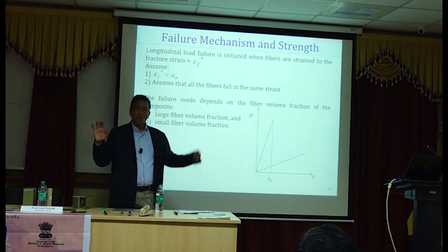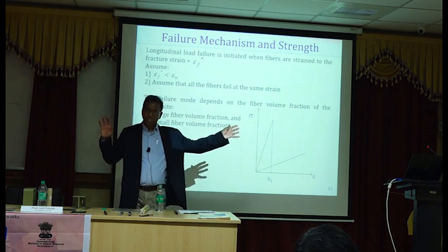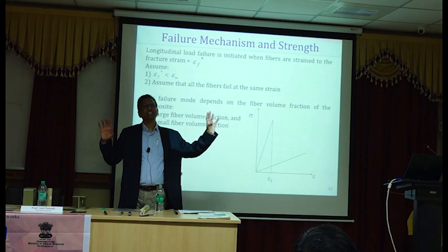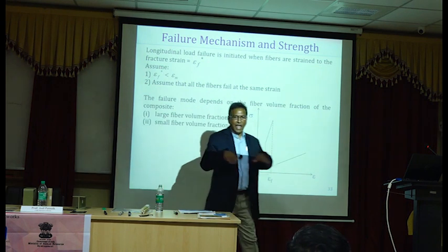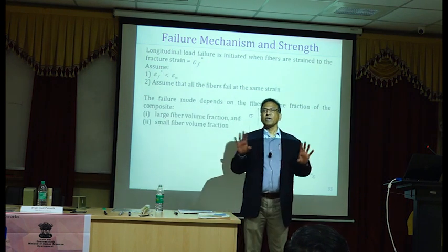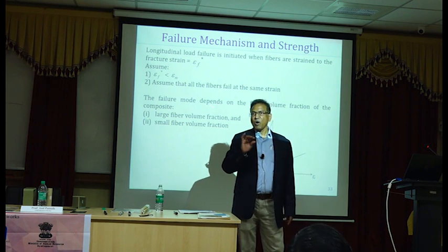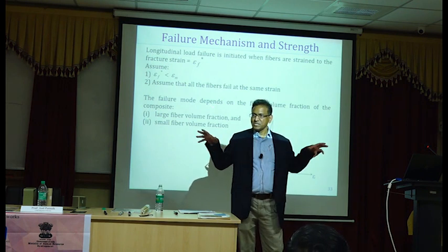Does it make sense? One is an uncracked section. That's where you use flexural tensile strength, which is also known as modulus of rupture, right? So if you don't provide any steel reinforcement, you apply a load, it will crack. It will act like an uncracked section all the way to failure, and it will become two pieces, right?